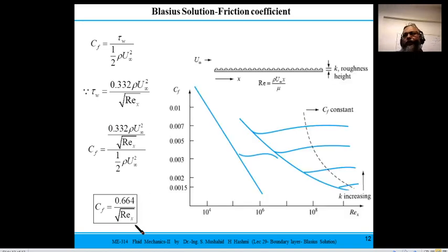So we have already seen earlier from order analysis that the friction coefficient decreases as the Reynolds number increases. So this is for laminar flow. As the Reynolds number increases, the friction coefficient decreases. And if you see the counterpart in pipe flow problems, using the Darcy equation, small f was your Darcy friction factor, which was 64 over Reynolds number.